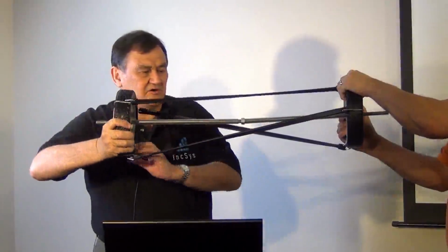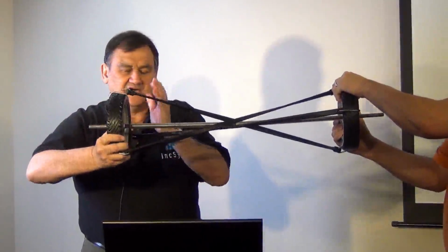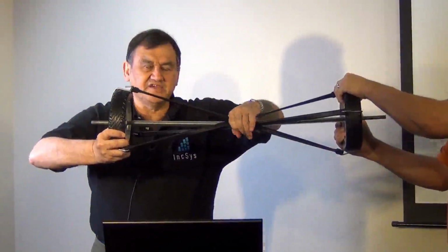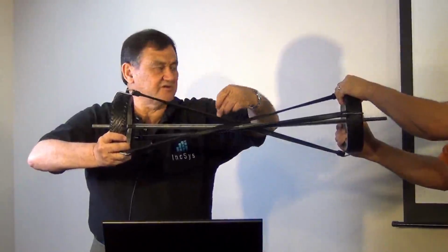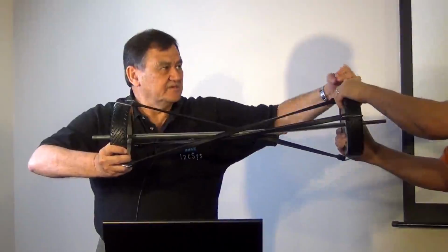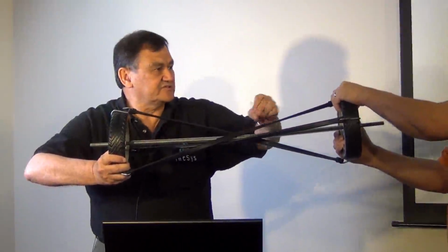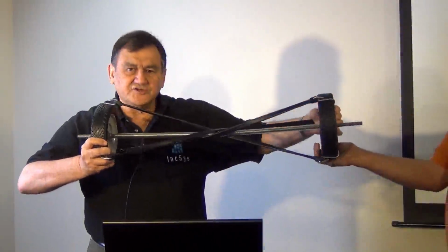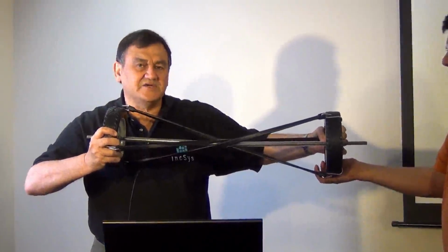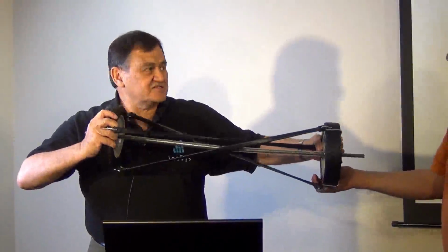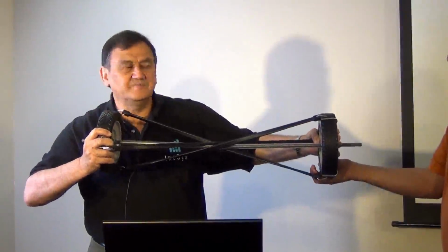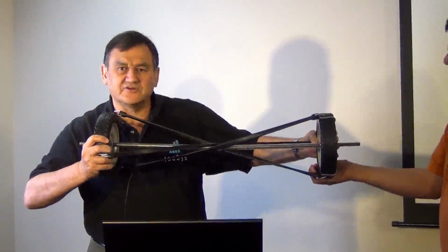As I advance my angle all the way to 180 degrees, I've got a fixed voltage, say of 500 kV here, and a 0 voltage here. I'm going to have a huge current flowing in this direction. At this point, I've got 500 kV, but it's out of phase. Again, I have huge current flowing in this direction. So that huge current actually absorbs VARs. The current drawn by that line is I squared times X. That's the big difference to understand: that line can be a huge consumer of megavars when it is 180 degrees out of phase.